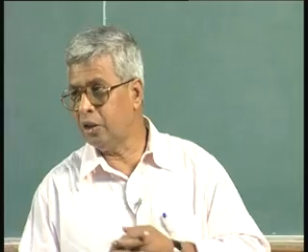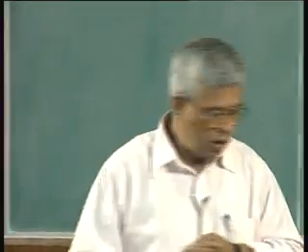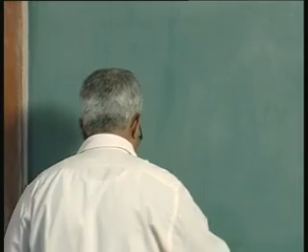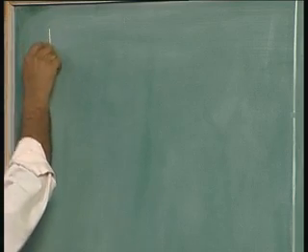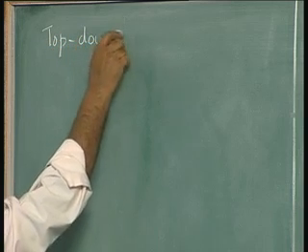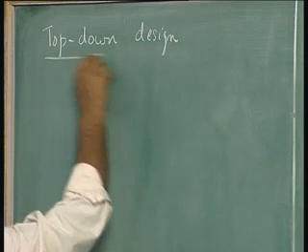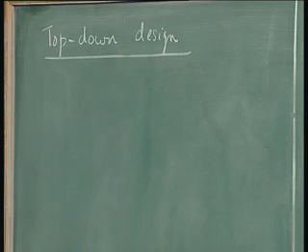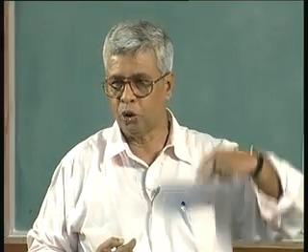So, this is what I want to teach you, the partitioning, another approach to top down design. Top down design works in two levels. The level we have been talking about is you define the problem, a complete overview of the problem, give complete specifications, input output signals, find out what you need, draw the state graph, and from the state graph we go to implementation.